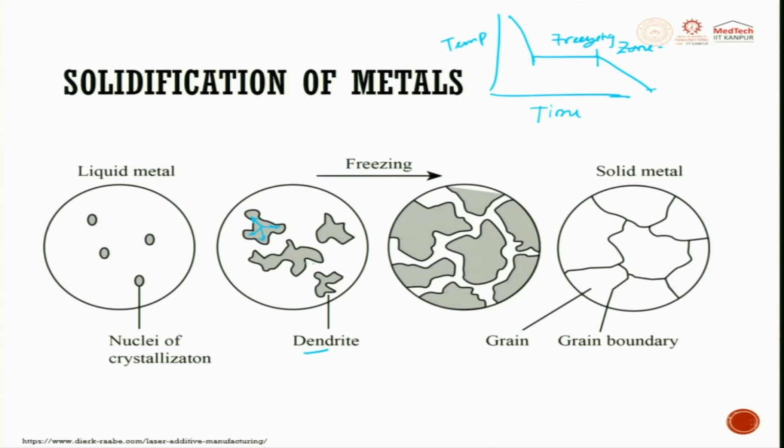The same phenomena is common in casting and also in additive manufacturing. The only difference is that casting has a large area, but in additive manufacturing you have a very small melt pool, created by a laser, which instantly solidifies and comes to room temperature as the laser moves. This is why in the process parameters we were discussing the ambience created around the powder bed fusion. This ambience prevents oxidation and also allows you to slowly form the grains and then they start growing.